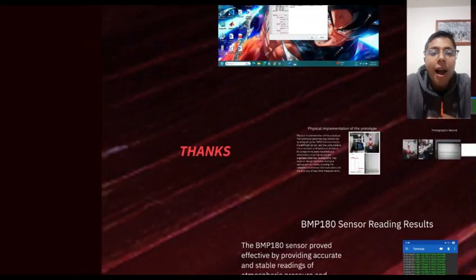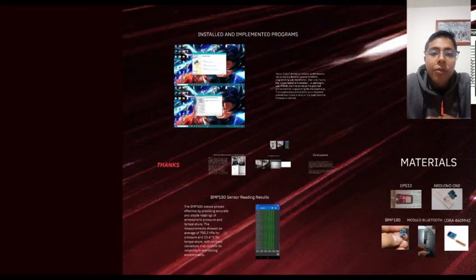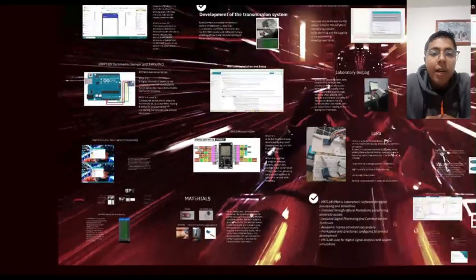As the receiver node, an Arduino Uno microcontroller board was combined with another LoRa module to capture the transmitted data packets. The received data was then forwarded wirelessly to a mobile device using an HC-05 Bluetooth module based on UART, universal asynchronous receiver-transmitter signals. Before testing, continuity checks were performed, verified with a digital multimeter, and stable power was ensured, delivered through USB and regulated supply lines.